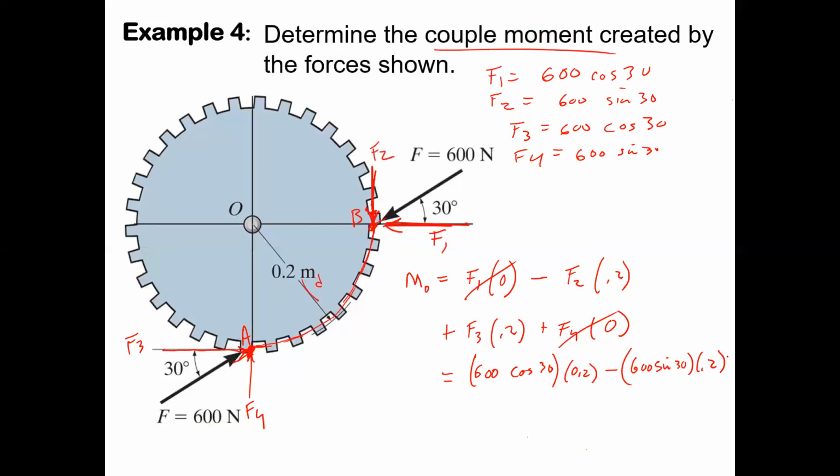It's complicated because you have 4 forces you have to think about. Where's an easier place to do the moment that would give us the same answer? B or A? Yeah, A or B would be good, right? Let's try the moment about point A. Moment of all those forces about point A means you can ignore F3 and F4, right?